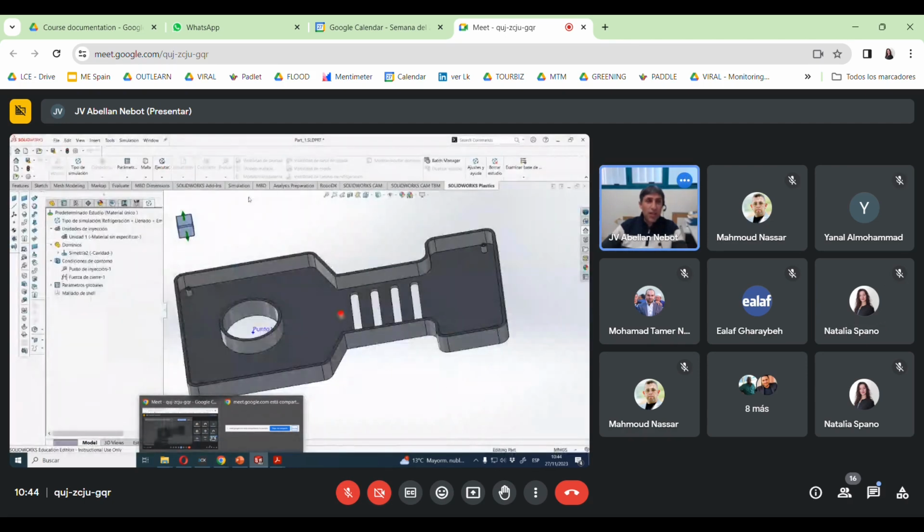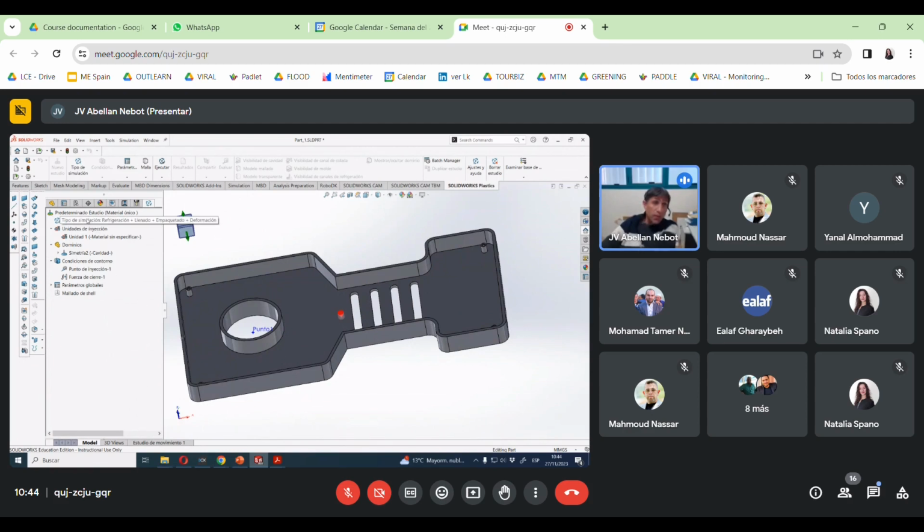It's okay, probably it's okay because you are using the same files like me, but maybe you have to click here in new study, and if you have here new study, then the program asks you the type of study. We have 2 types of study, a solid study and a shell study. If the part is thick, we should use solid. If the part is thin, you should use shell.